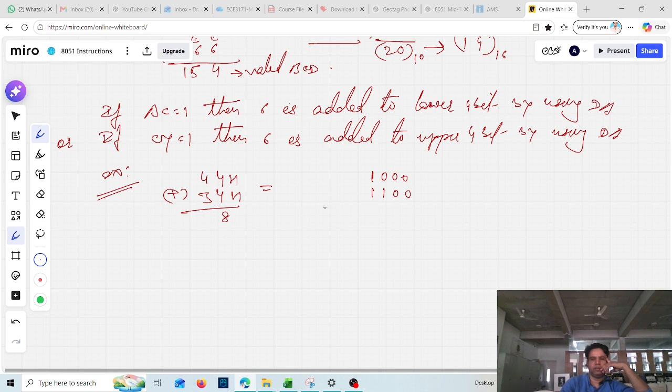So fine, let us consider this one. Suppose that we are adding in binary form. So 0, 0, 0, 0, 0. I'm going to show it in carry form. So let's suppose that we are going to add this. Now if you are going to add 1 plus 1, you get 0 and a carry will be there to this one. And you can see here, because of this carry, the auxiliary flag will become 1.